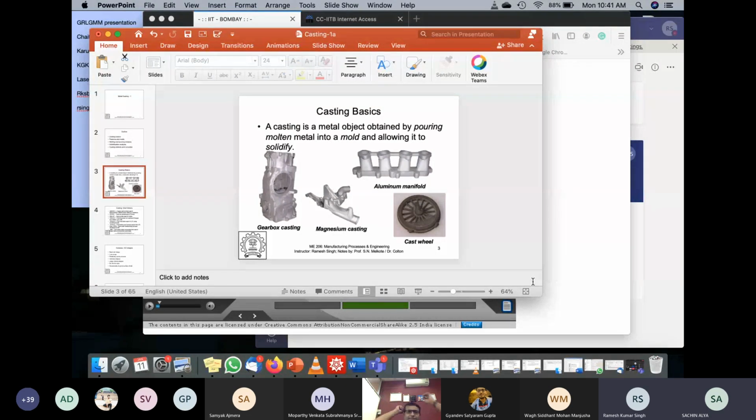A core you can break it. Since you have access to the core, because the print will be there from the top, you can go ahead and use a chisel, hammer, something to break it. So the core can be broken. You can take some sort of a chisel and break the core out of it. Core always has access because it's a hollow thing, right?